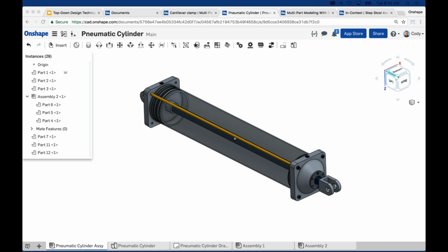How do I move an instance to another existing assembly in the hierarchy, not create a new one? You should be able to drag from the instance list. Drag the part from one assembly to another one in the instance list.